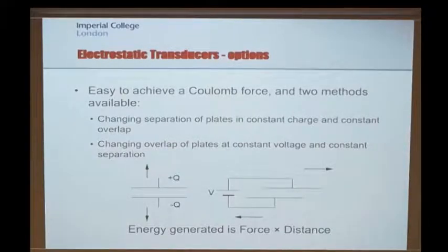Of course, you can move between those two extremes, but typically what you will see for the electrostatic approach is people operating in one or the other of these modes. If you have a parallel plate capacitor where you separate the plates away from each other and you operate those in constant charge, in other words, you have the capacitor in a closed position, you squirt some charge onto those electrodes so there's a voltage, you then disconnect everything from those, and then you separate the plates so that charge can't move anywhere, then you generate electrical power, and actually you'll find that the force between those plates